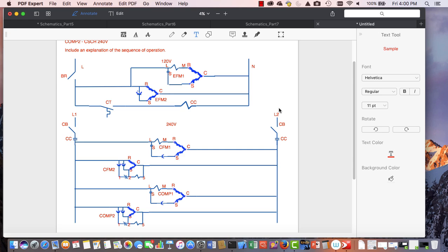Okay, this is the basic of a commercial refrigeration system where there's an indoor unit that's in the cooler and an outdoor unit that might be on a roof or behind a building or something like that. Okay, notice there's no transformer. We're still using line voltage, but we're using two different voltage sources, two circuit breakers, and two different levels of voltage. And the outside unit is going to be pretty heavy amperage. The inside unit will be lower amperage.